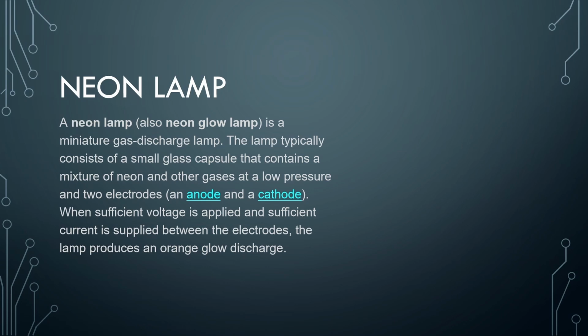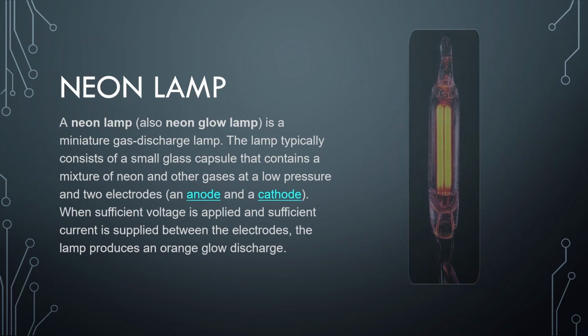There are different types of neon lamps. The standard neon lamp emits a characteristic red-orange light, primarily using neon gas, in decorative lighting and indicators. The advantages of neon lamps are that they have a long lifespan, low energy consumption, and a bright and eye-catching color. The disadvantages are that they are fragile, require high voltage, and have limited specific applications.